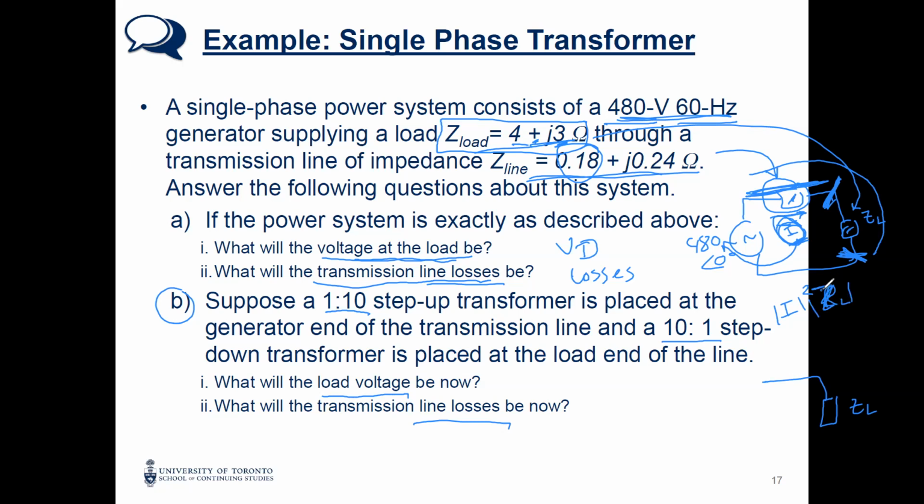Yes, if you use the ZL, now it will not be just the active power losses, but plus the reactive. But we cannot use the impedance magnitude. We will add R here, and say this is for the P losses, and then we make Q loss. Let's say losses. It's absorbed, but let's say losses: I magnitude squared times the X of the transmission. It will be the active and reactive power absorbed by the transmission.